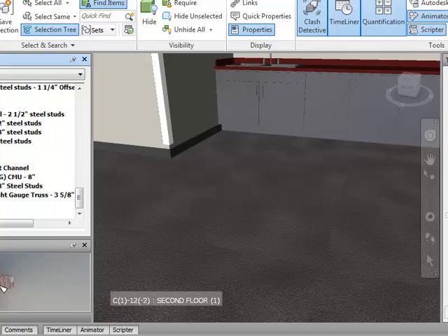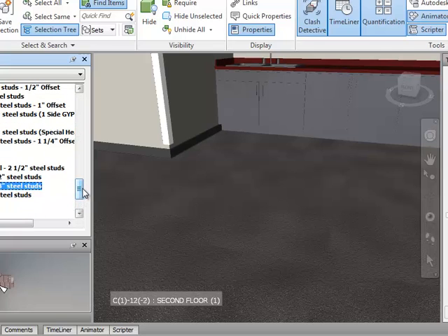Maybe under 1 hour, 2 hour was drywall. So 1 hour will be drywall, yeah. Because sometimes a shaft wall will be, I guess always a shaft wall is going to be a drywall setup, usually 2 layers of gyp on each side. You'll have CMU walls that will be your core walls around elevator shafts. A lot of times those will be CMU, or they'll be a shaft wall with gyp board.